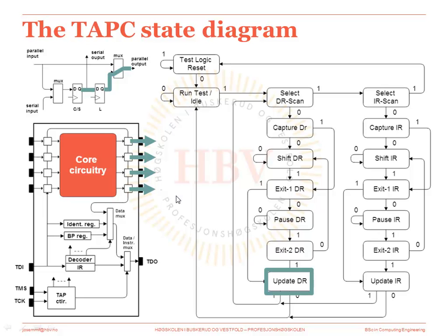And then we just have to repeat this sequence, going from update into capture to capture the test responses, and then from capture to shift, so that we shift out the test responses and shift in the new test vectors.